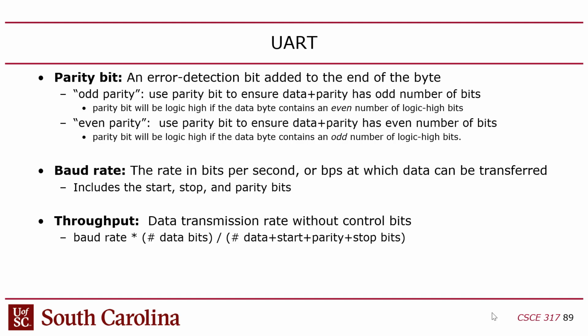So how does it know what the payload looks like? Like, it must know to look for 10, 11 bits, right? Yes. Both sides have to agree on the number of start bits, number of stop bits, number of parity bits, and they have to agree on the clock rate. If I'm sitting on the receive side of a UART channel, whenever the channel's idle, my receive line is just going to be high. The second that goes low and there's a falling edge, I know something is coming in.